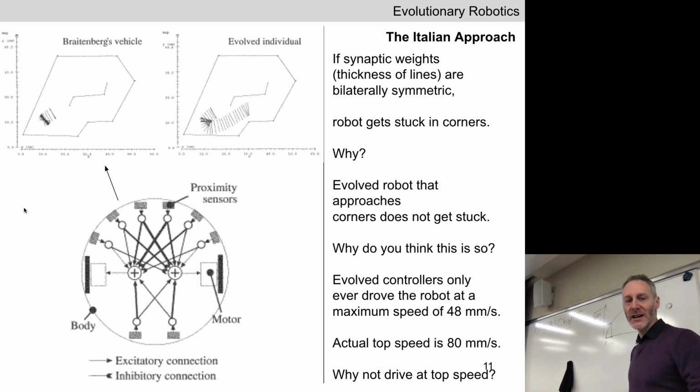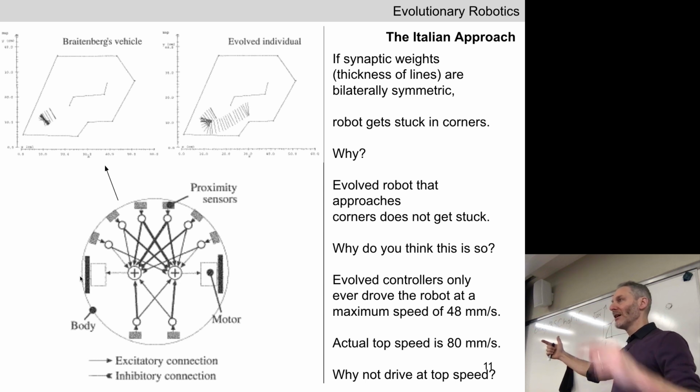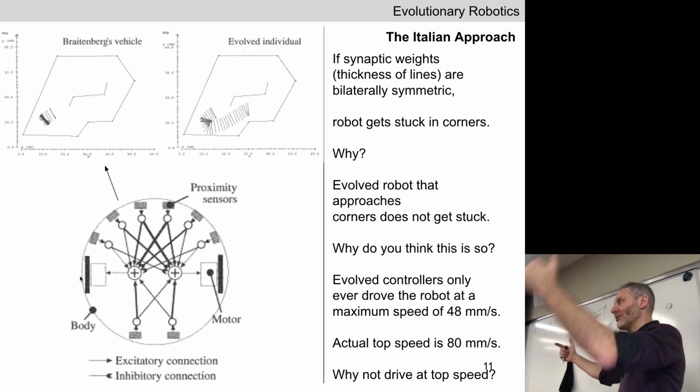Coward with the walls, yes. So when the proximity sensors on the front left were firing strongly, meaning the front left of the robot was close to a wall, that should inhibit the contralateral wheel. So something approaching from the front left should cause the right wheel to slow down relative to the left wheel. The left wheel is now spinning faster than the right wheel.